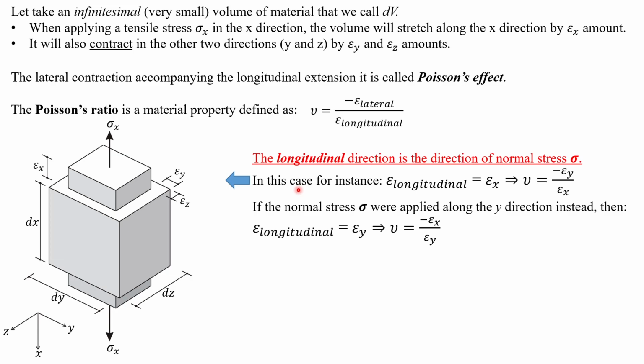The nice thing about when you get answers that are wildly wrong, what any good engineer should do is look at the answer and go, does that make sense? Can that rod extend 5 metres if it's only 200 mil? No, it can't. So just make sure you look at the answers and go, have I made a mistake? Right, I've made a mistake. Where have I made a mistake? It could well be you've got these messed up.